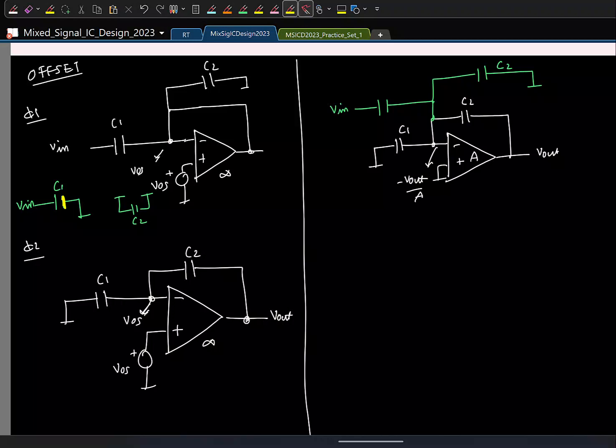So let's finish the circuit, right? Here, to get the error voltage, I need to do a charge transfer once with one set of capacitors C1, C2. If I do that, I'll get the error voltage here, right? But then, using that error voltage, I'll sample the input and reset the capacitor. So basically, we need one more set of capacitors. Let's say I call this C1 hat, C2 hat.